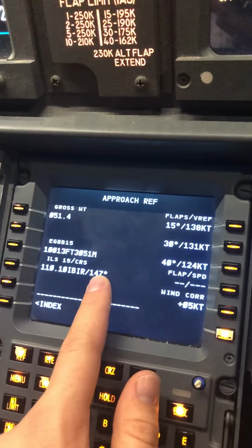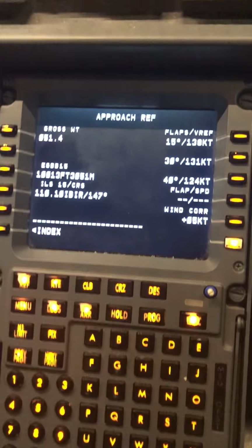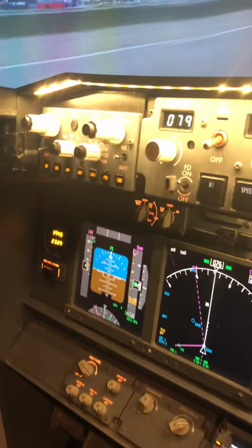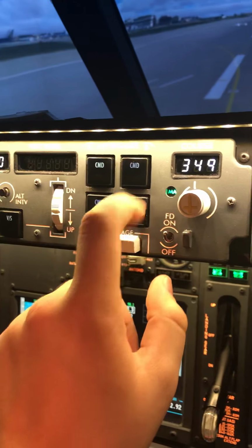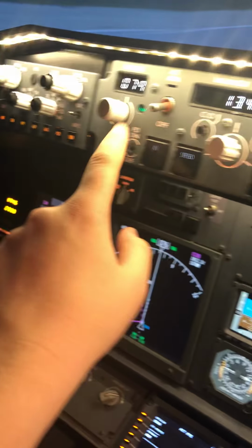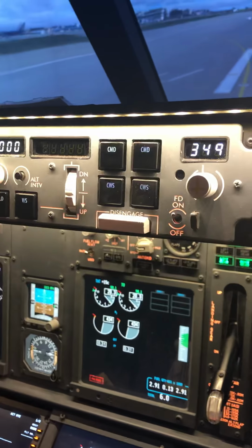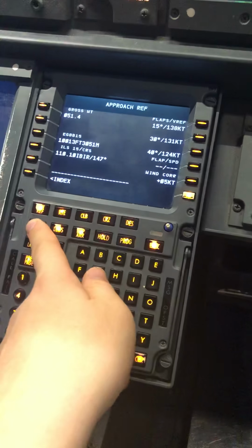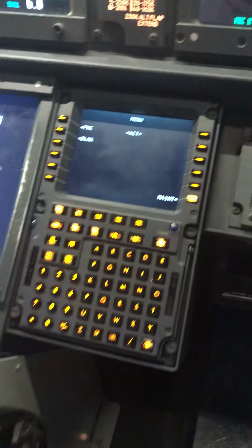So that gives us that information, which is obviously quite useful when we go into ComNav. And obviously we would set the course 147 up there. Something to bear in mind, because this course knob isn't working at the moment, something I've learned today is make sure that the captain's side has the master flight director. Otherwise it will start doing some really, really crazy stuff. But in short, that's probably about everything you'll need to know for the flight management computer to get everything running.